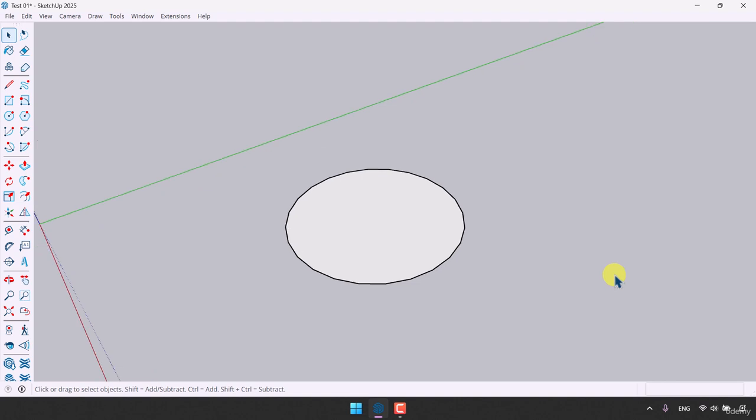And for the rotational copies, I can click on the line option, move my cursor to the edge of the circle, hold it for 2 or 3 seconds, and move my cursor slightly to the center point. So I'm going to click on it like that, draw a line like that in here.